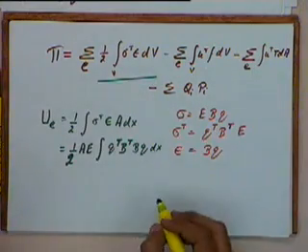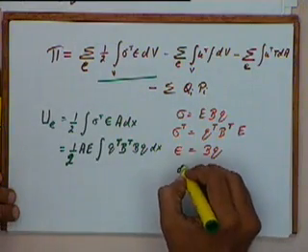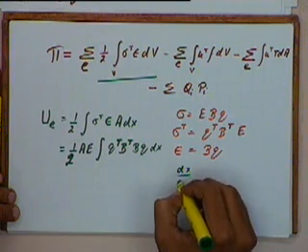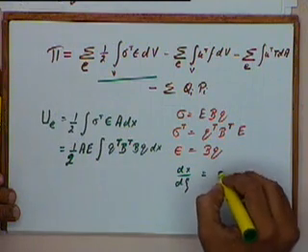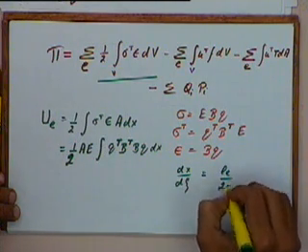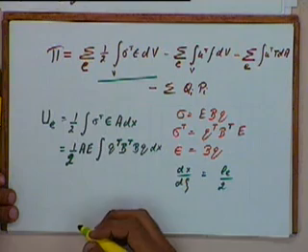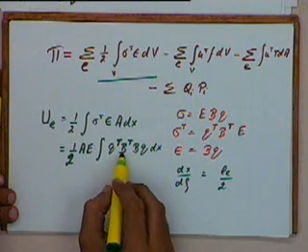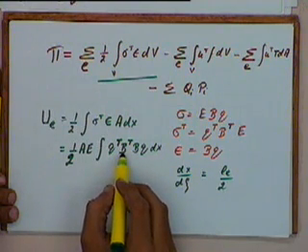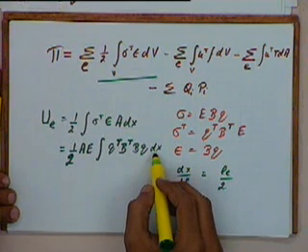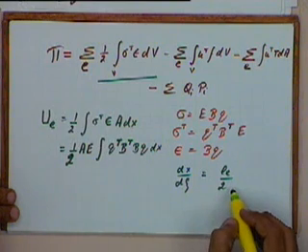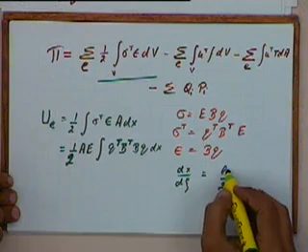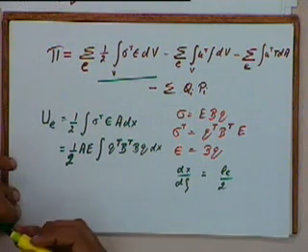Okay, and earlier we have also used the fact that dx by d zeta is going to be equal to LE by 2, because my B matrix is in terms of zeta. So, I prefer to do the integration with respect to zeta rather than with respect to x, and that I can convert by using this relationship. So, dx is equal to d zeta into LE by 2, I can put that over here.